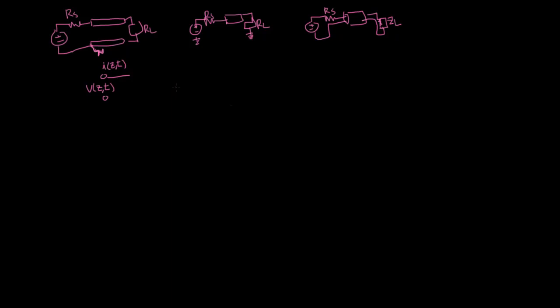What happens inside a transmission line can be stated quite easily: on one hand, the current doesn't want to change immediately, and so that takes place in the form of a series inductance. So we're going to have this little bit of series inductance. When we talk about this inductance, one thing important to note is that this is an inductance per unit length. So this L is actually in units of Henry per meter, not just Henrys like you would usually see.